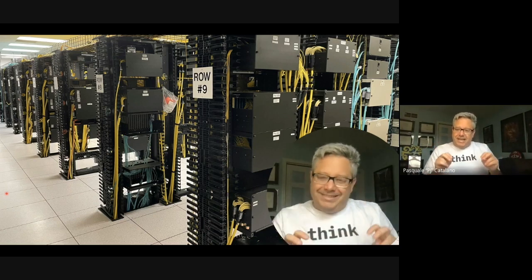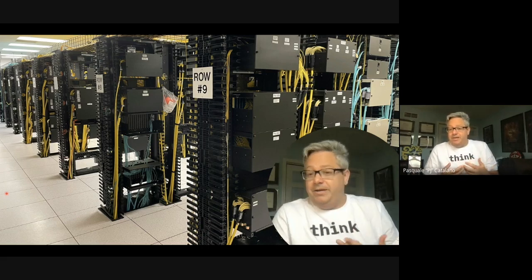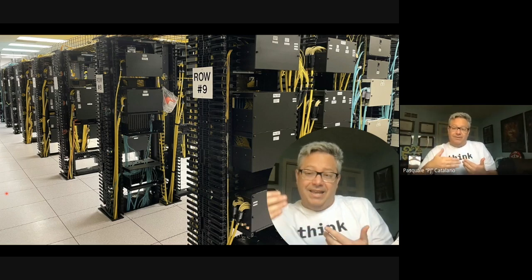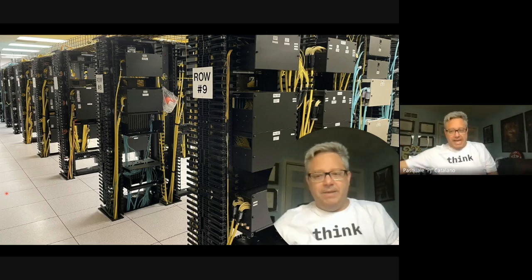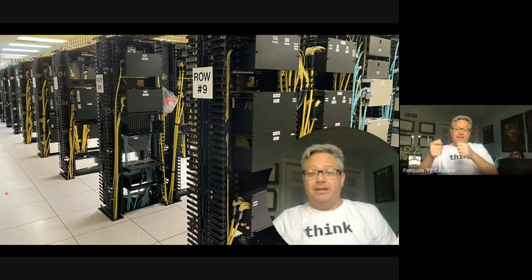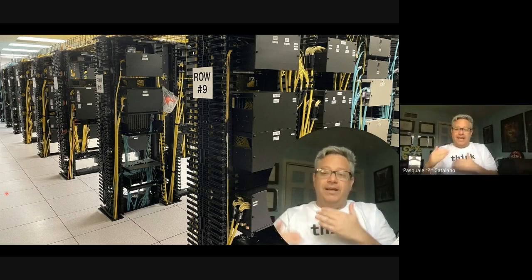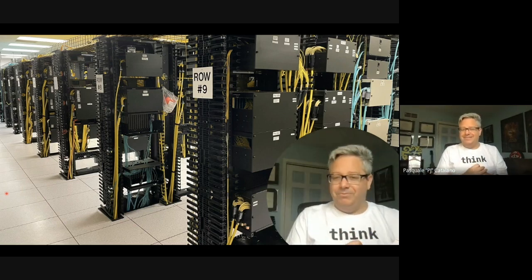So the distance statement is a little bit of a misnomer in the industry. It's the way it's been, but basically it's telling you how much power it has. Then you can convert it: it's really not 10 kilometers if I go through 3 patch panels. It's maybe only 8 kilometers. But if I have to go 3 buildings, I might have to go through 6 of these patch panels, because every building has a patch panel. So that's how that 10 kilometers gets eaten up, because it's really just a power statement, not a real distance statement.